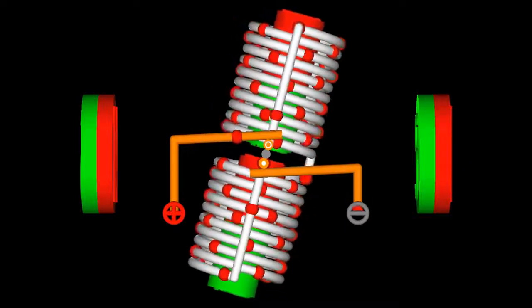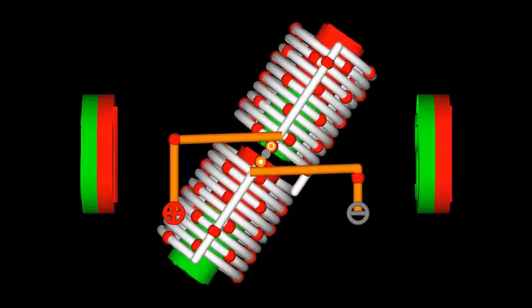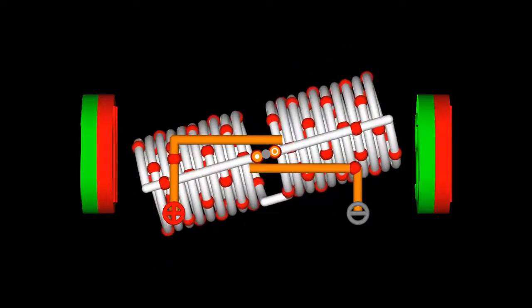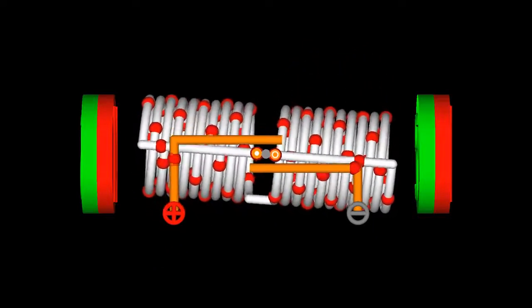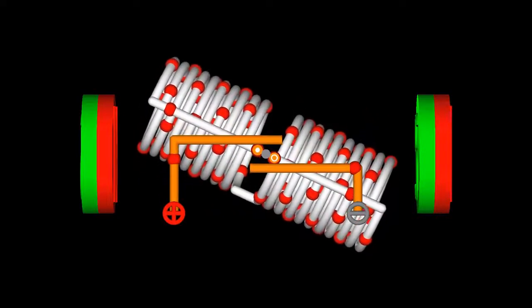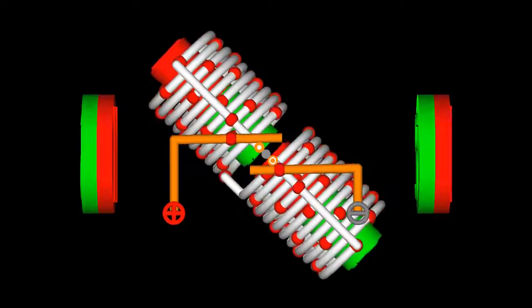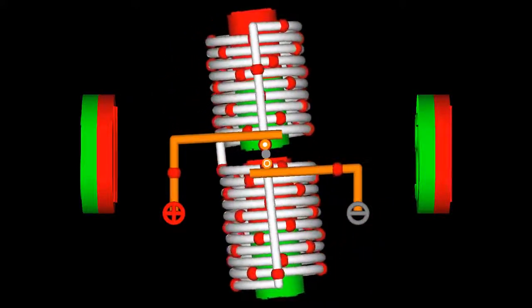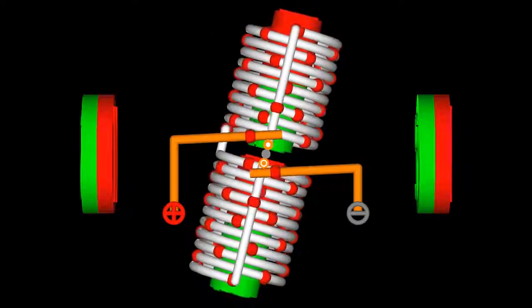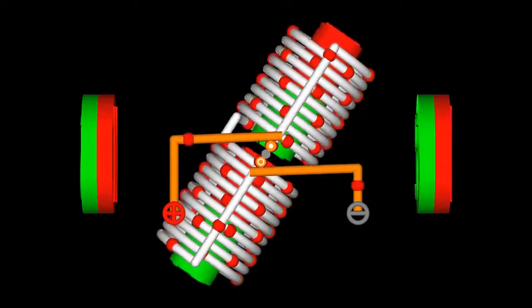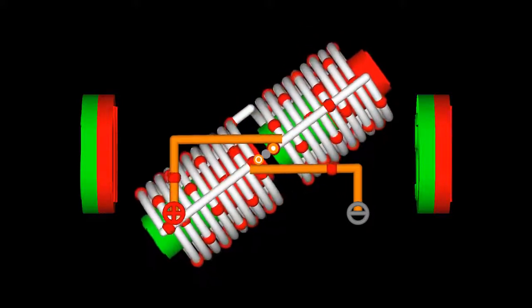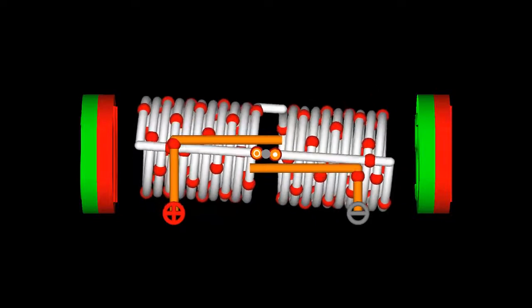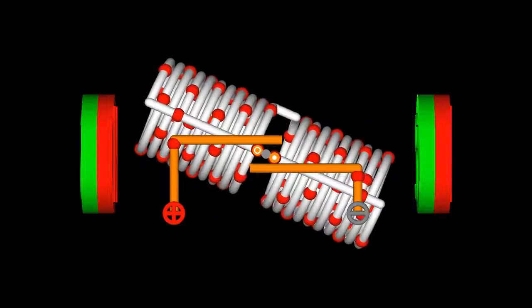The rotary switch of a DC electric motor that periodically reverses the current direction of the electromagnet is named the commutator. The switching contacts running to the supply voltage are named brushes. Early machines used brushes made from strands of copper wire to contact the surface of the commutator. Even if modern rotating machines almost exclusively use solid carbon contacts, they are still named brushes. With the commutator, the electromagnet spins continuously if exposed to the magnetic field of the permanent magnets.